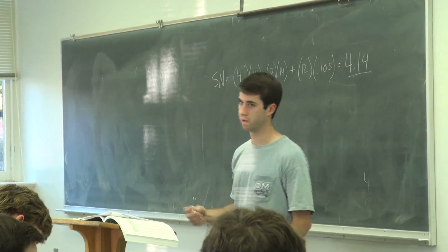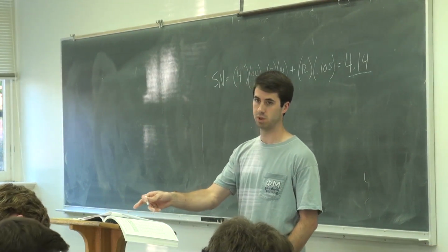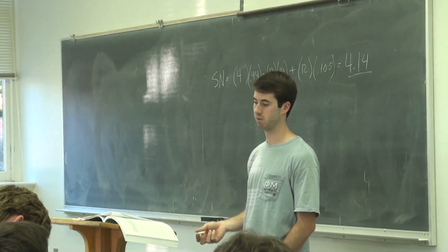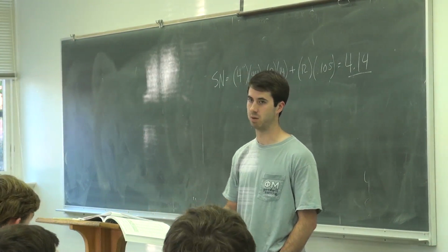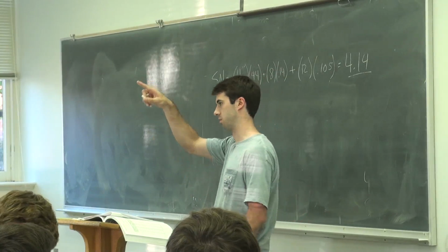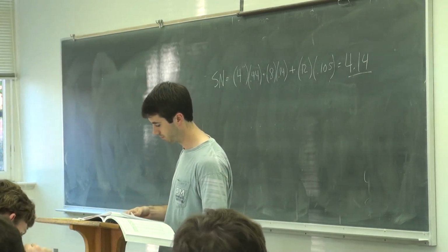If we were designing, we would take an equation like that long equation on the previous page, or some kind of nomograph, similar to this chart at the top of the page, where you start here, go a line up, then a line down, and all that. You figure out your required structural number.